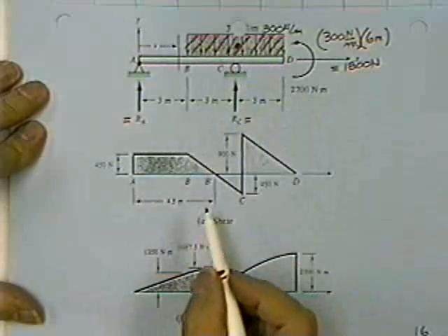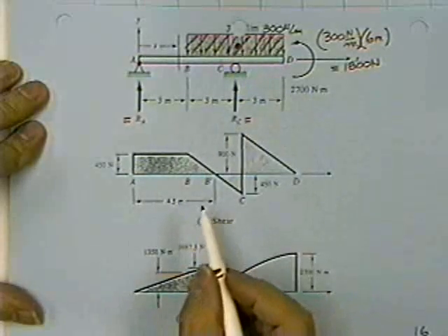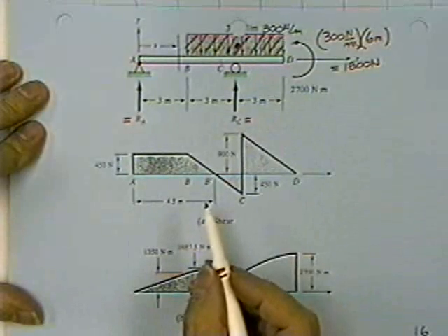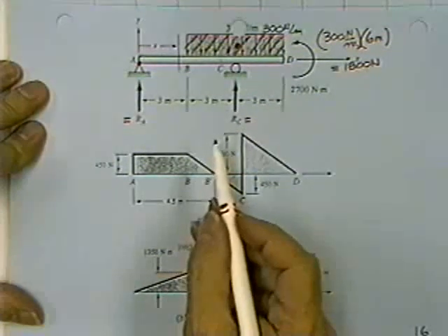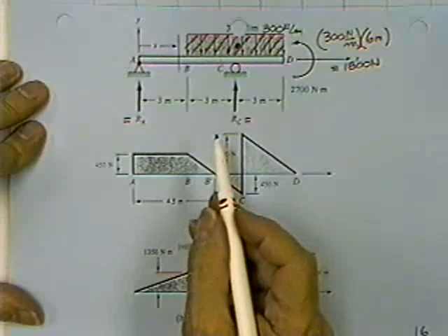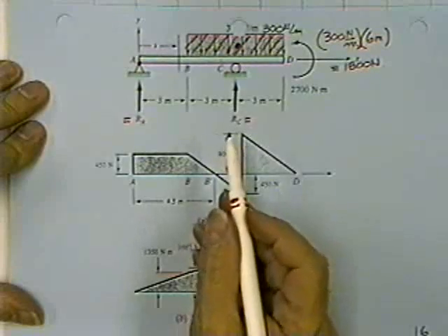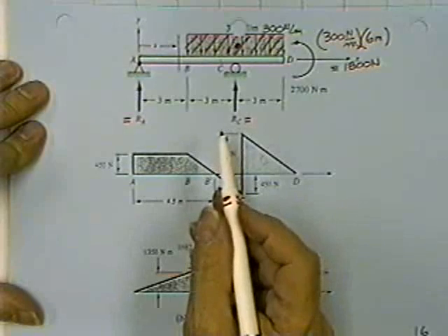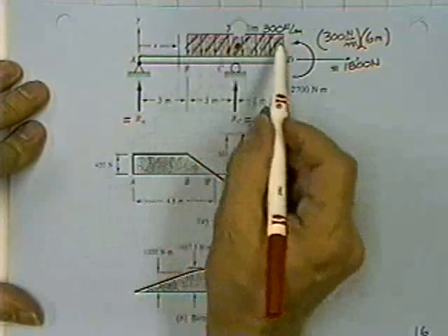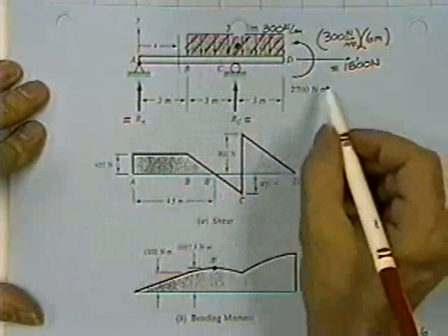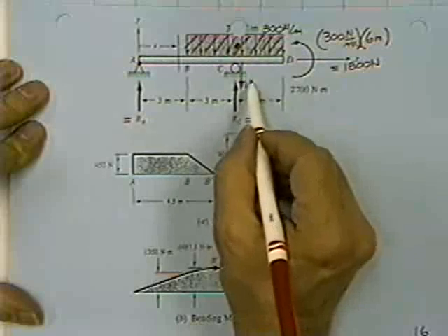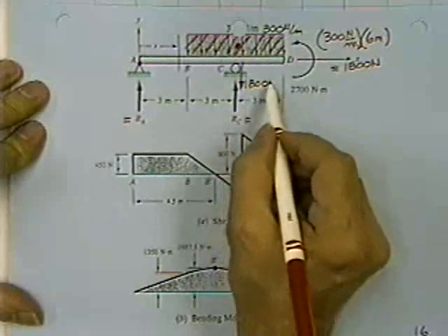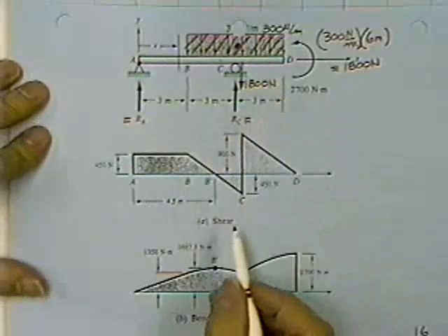Now what you have to be really careful about is not to leave that lie on your load diagram. Because if you forget and draw the shear moment diagram for this untruth, it's going to look totally different from the real moment diagram. As soon as you find the reactions, it's legal to do that, but then it'll be your job to take this load and spread it back out like it really is. Alright, so I'm going to put 1,800 newtons. I'm going to show it a little bit off just so I can see it.